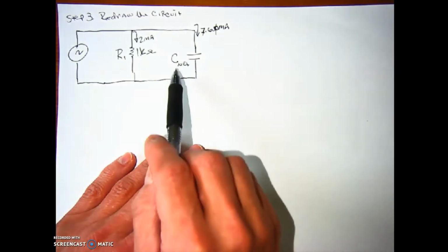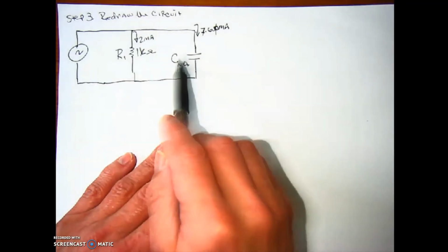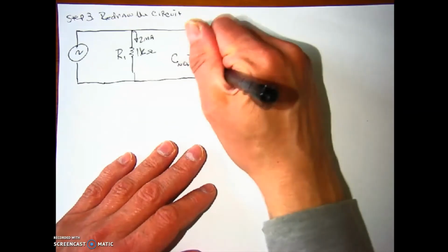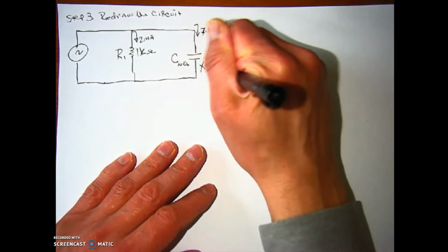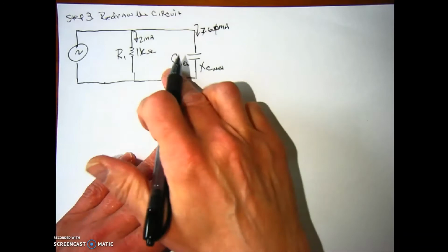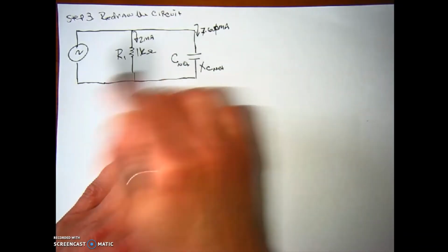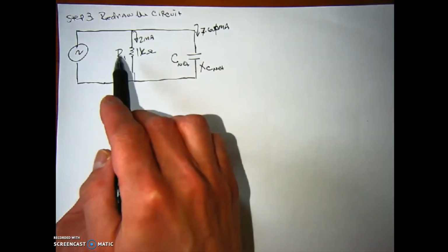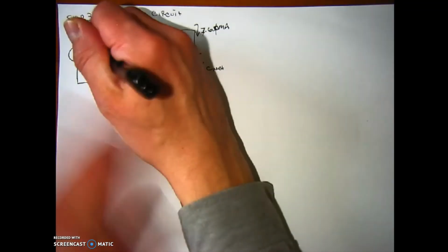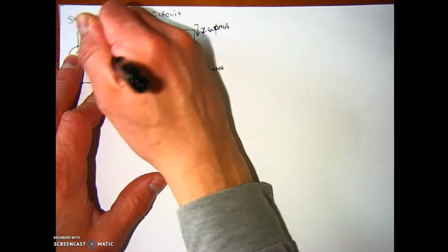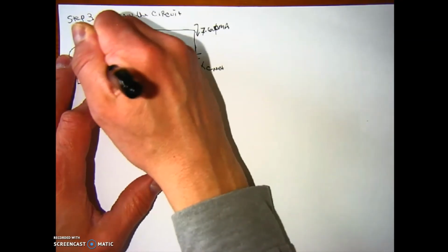So what we want to do now is solve not only for the x sub c net, but also for the C net itself. This is what we call the equivalent circuit. In the equivalent circuit, we have our source voltage, which was 2 volts peak at 1.2 k hertz.